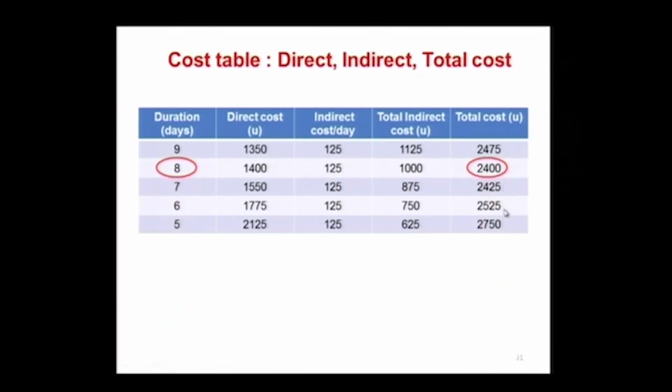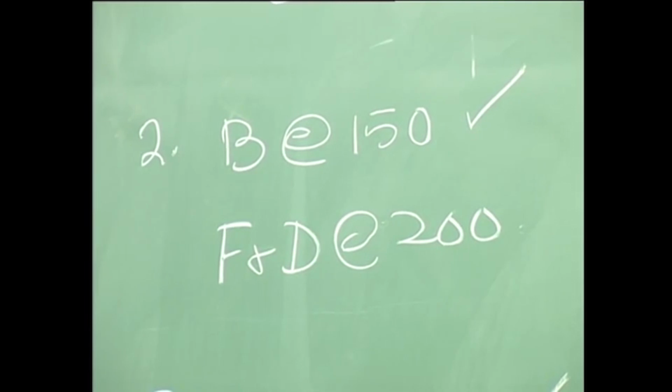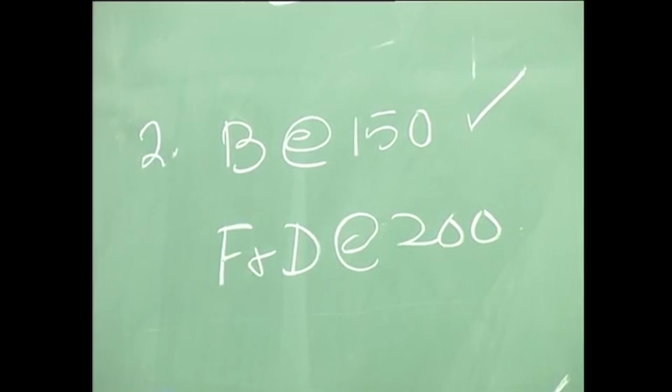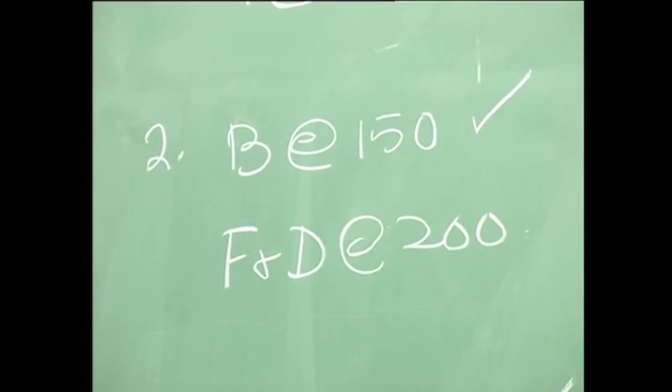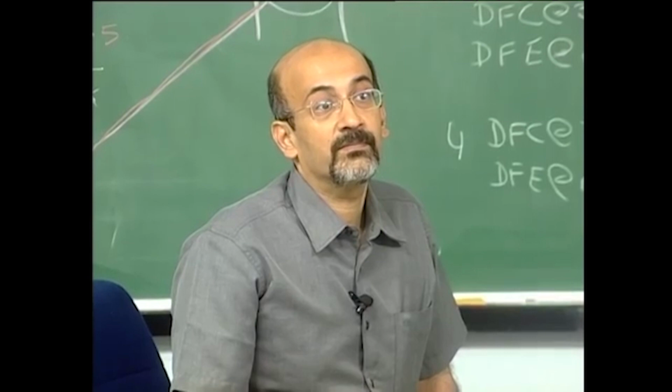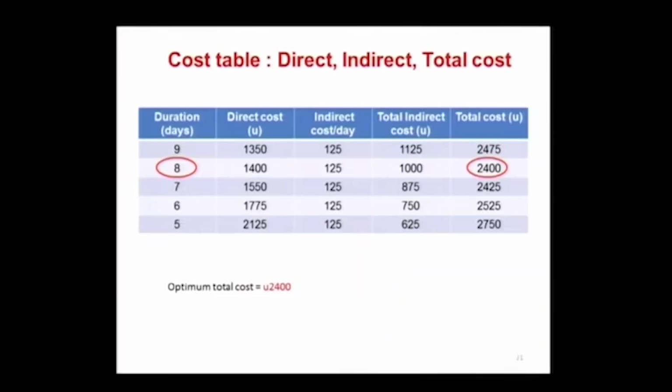Okay, then it starts increasing. We can see the first cost we incurred was 50, after that it went to 150 on the second day. Remember, the increase in cost in the second step, by bringing it down for 2 days, went up by 150, whereas the slope of the first one was only 50. What is the indirect cost? 100. So after that any reduction cost us more in direct cost than savings in indirect cost. That is why the first step is where the savings come.